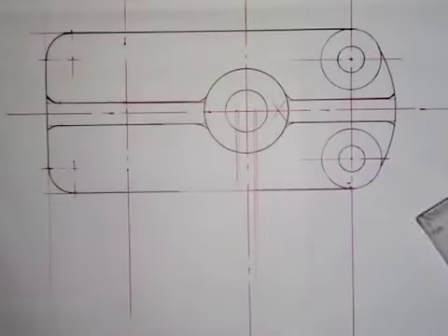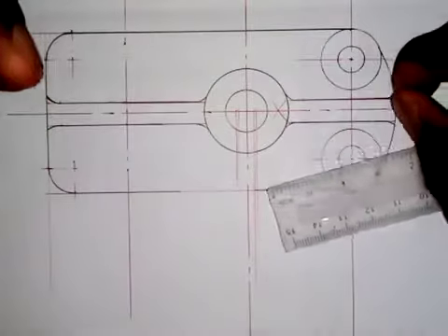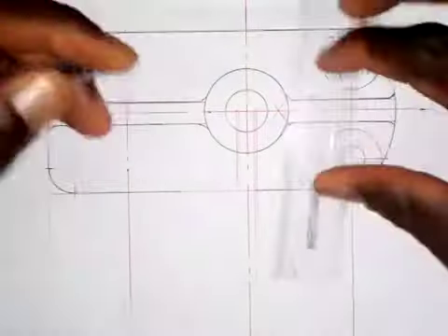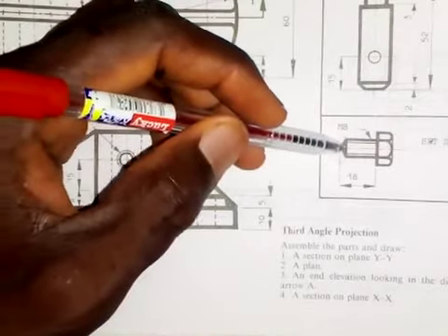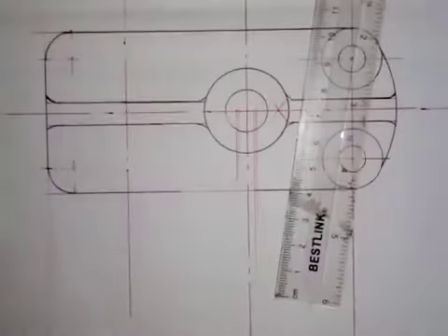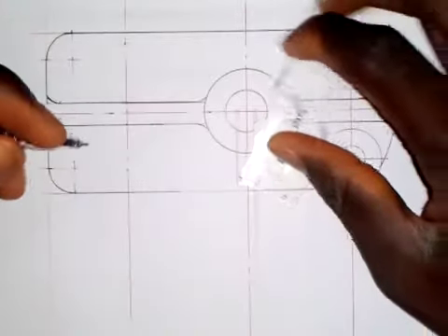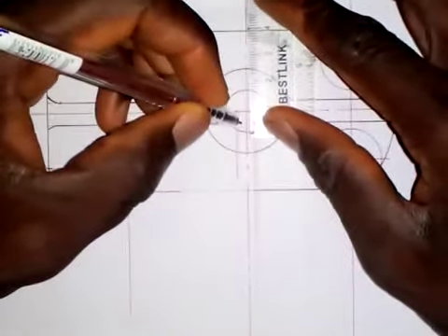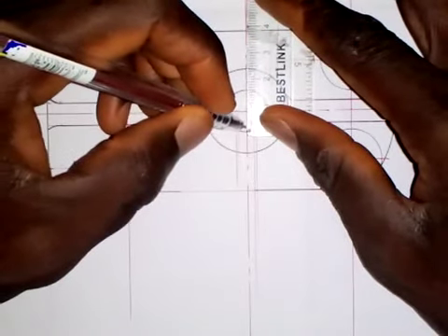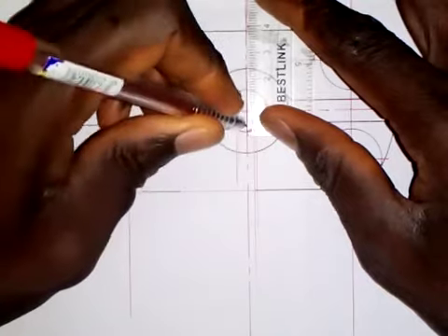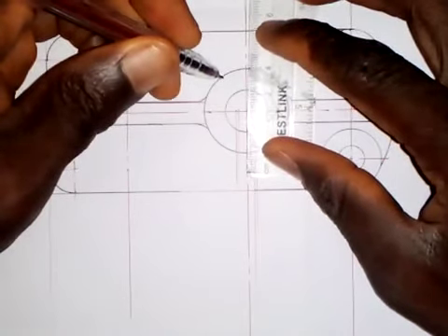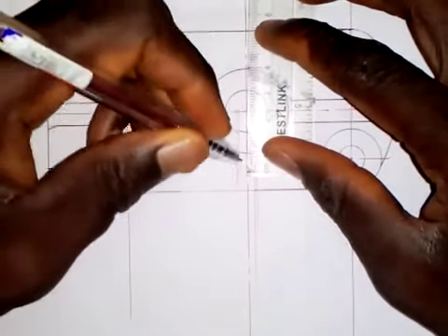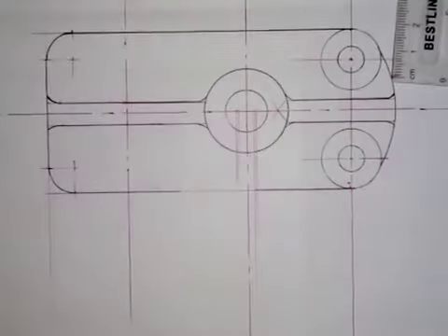so the set screw, the length is 18 millimeters. The length is 18 millimeters. So this end that we have here that is pointed, the distance from here to here is not given. So what I will just do is I'll take a measurement from this point here. I'll take a measurement of 2 millimeters in here. Okay, so from these 2 millimeters here, I'm going to take a measurement of 18 millimeters. So this is 18 millimeters here. So here I'm going to draw a horizontal line.